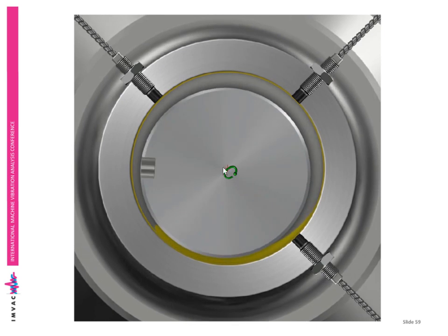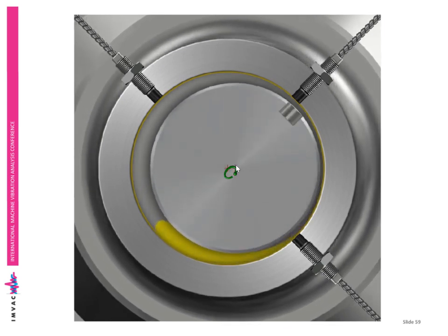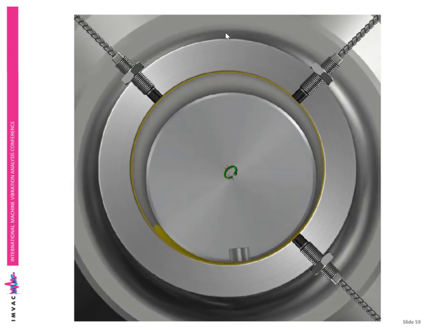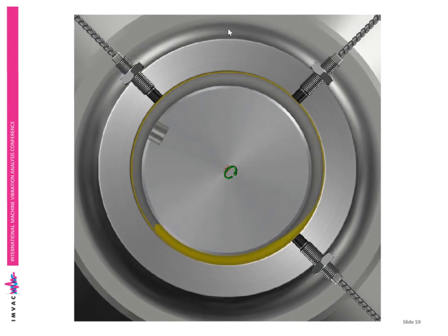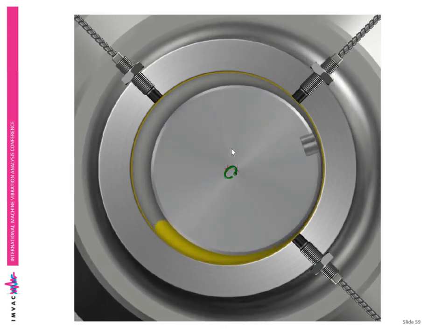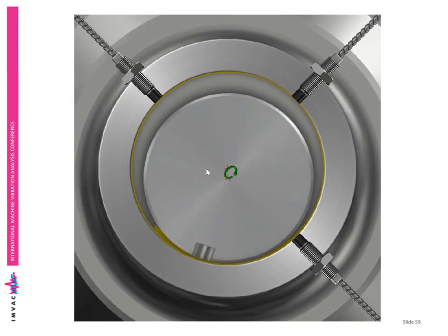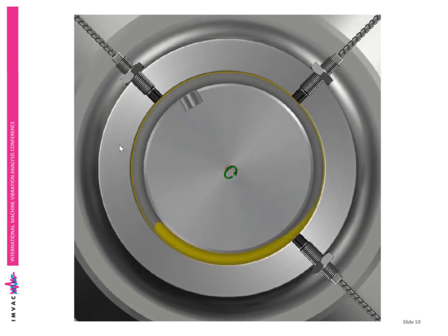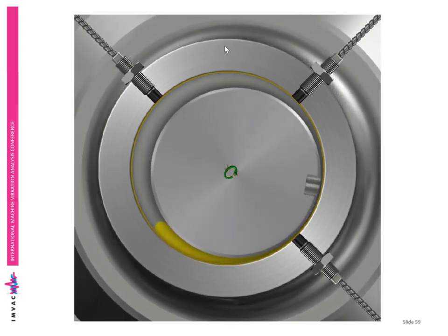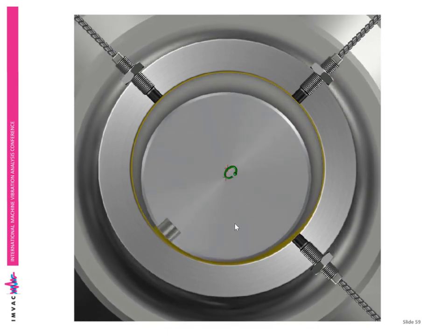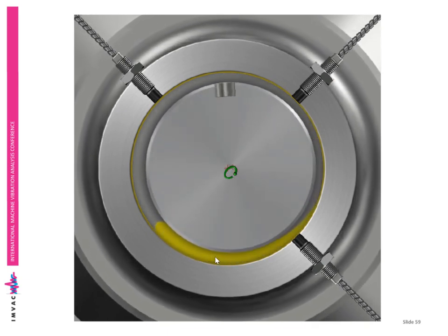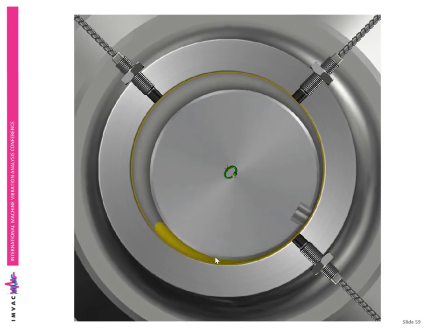Now, it means that this vibration is being cushioned. And therefore, if we have an accelerometer sitting up on the bearing housing somewhere, we would be expecting this vibration, this motion, to be transmitted through up to where the sensor is located. And this film of fluid, this little wave under there, really deadens that vibration.